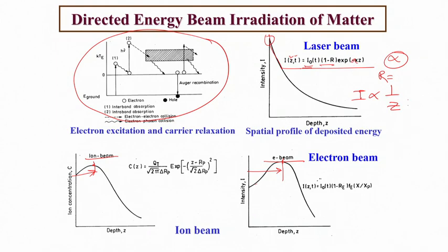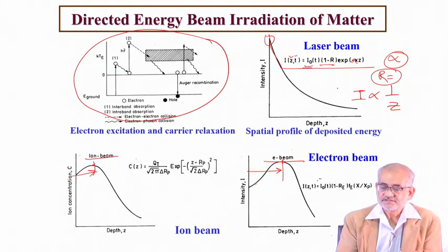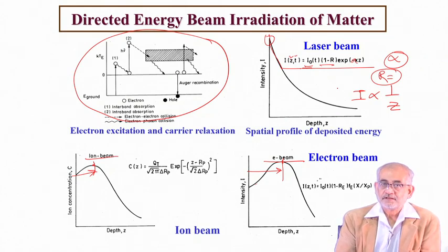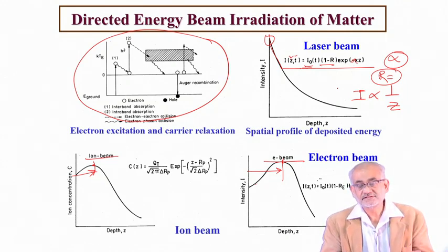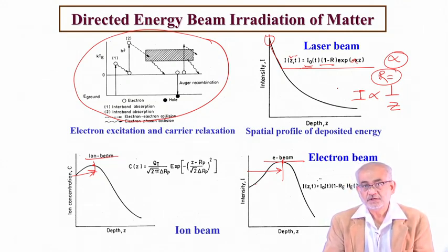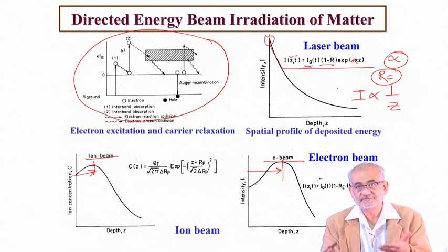So one would like to play with reflectivity. One can use certain films or coatings or make the surface rougher so that the coupling efficiency increases. Reflectivity is simply this: if 100 radiations are incident at a given point of time in a given area, how much of it is able to interact and couple, and how much is reflected back.